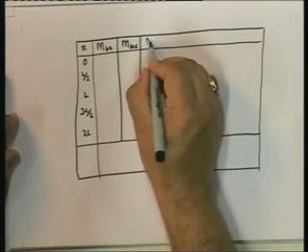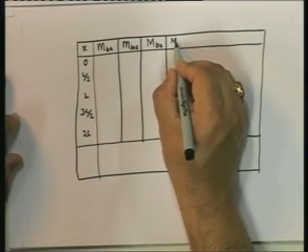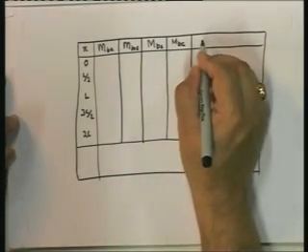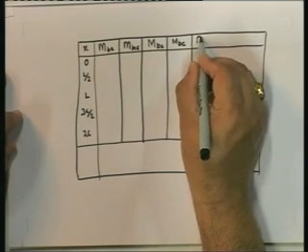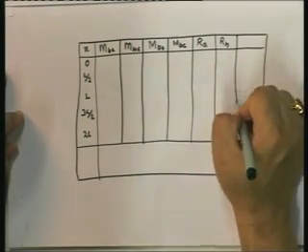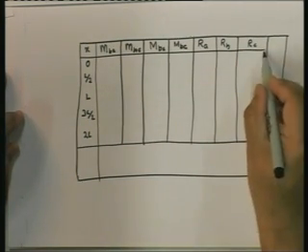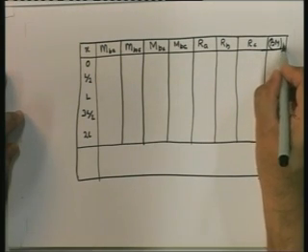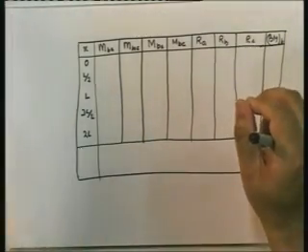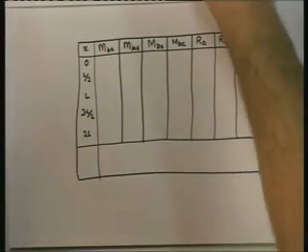From that we can find out the moments at the ends, BA in member AB, and MBC, and once we find out these, then we can find out the quantities that we are interested in: RA, then RB, RC, and then I'll just draw another line for the bending moment at B. Okay, so now the first step is to find out these values, and I'm going to spread out all these in front of me so that I can find out each one of them directly.